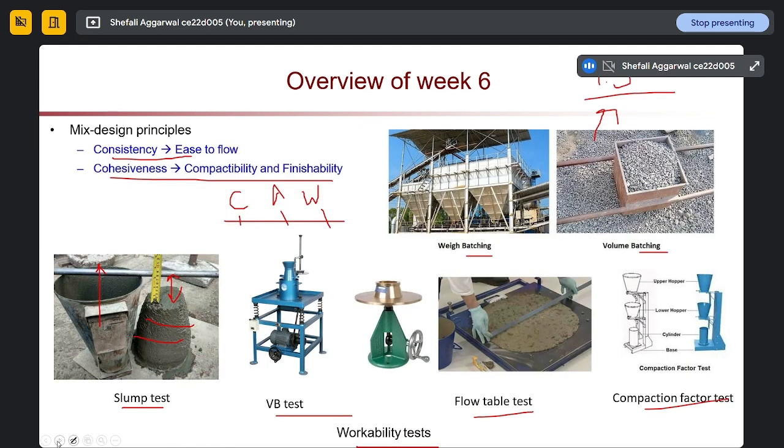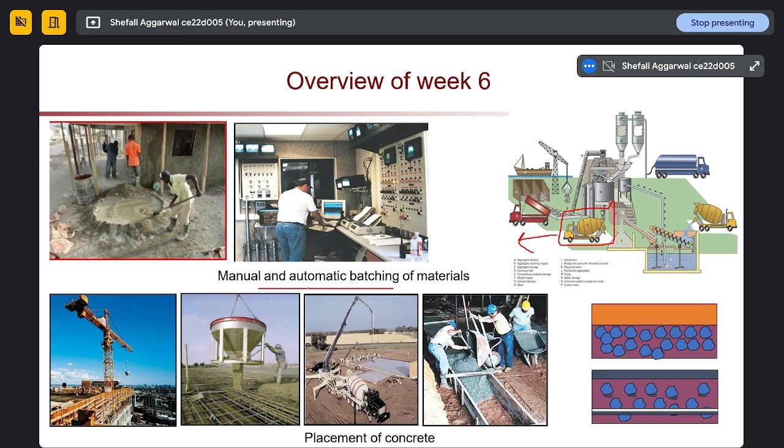Other than this, you can see different kinds of other raw materials or other waste materials which can be the source of these raw materials. So if we talk about calcium, generally we are using limestone as a source of calcium. However, instead of limestone, marl, calcite, shale, seashells, all these things can also be used as sources of calcium.